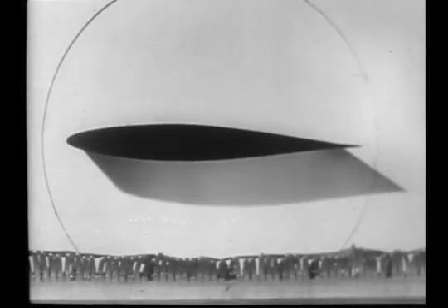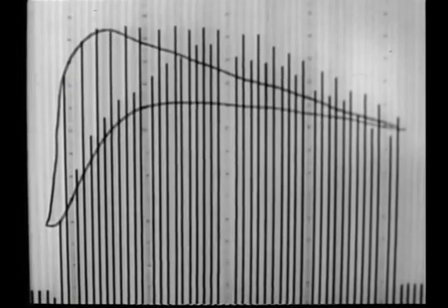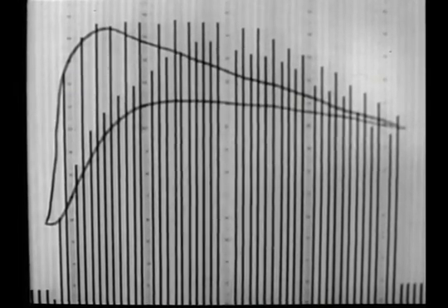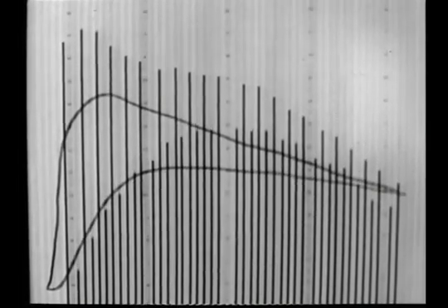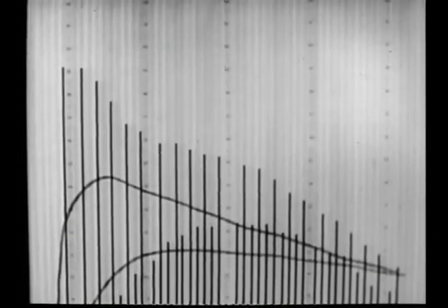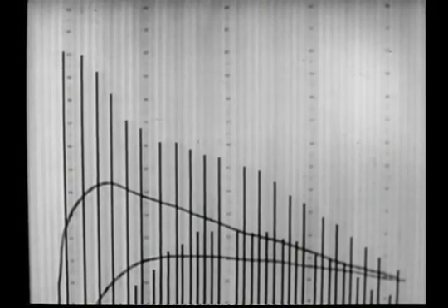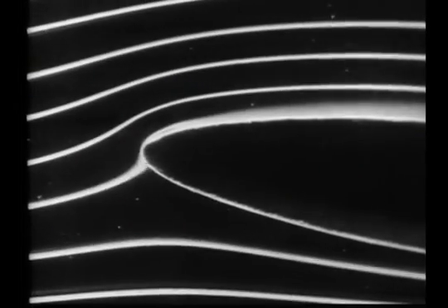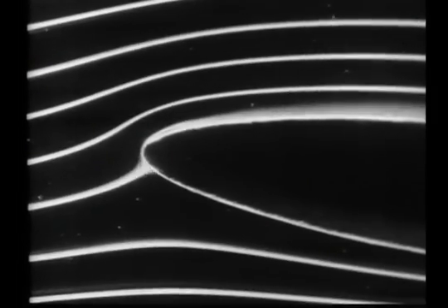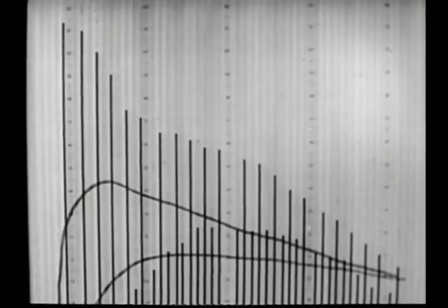As a result, at low angles of attack, the extent of the favorable pressure gradient over the upper surface is increased well beyond that of the previous case. As the angle of attack is increased, the situation changes radically. Because of the geometry of the profile, the radius of the leading edge is small. As the forward stagnation point moves downward, the flow passing over the leading edge must accelerate rapidly, producing this abrupt pressure minimum and strong adverse gradients.